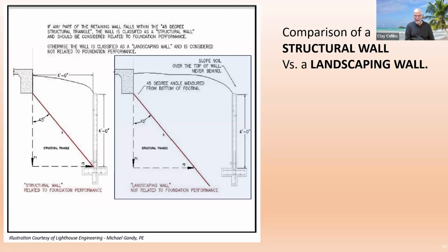It might have an impact on the foundation because of water, expansive soils, collapse of the soils, impact on the pool wall, etc. So just because there is not a retaining wall, if they put a pool there, that pool wall becomes to some degree a retaining wall, whether it's landscape or structural. That will have a huge impact on the foundation if you're not careful.